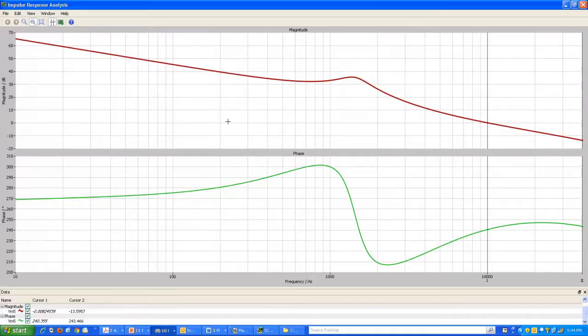Another important information that we can verify on the loop gain plot is that at low frequencies, so I plotted only from 10 Hertz, so even at that frequency, the gain is more than 65 dB, so that's more than a factor of 1,000. And when I go to 1, it's going to be another order of magnitude higher, and so on. So the DC gain would reach infinity if we can go all the way up to 0.